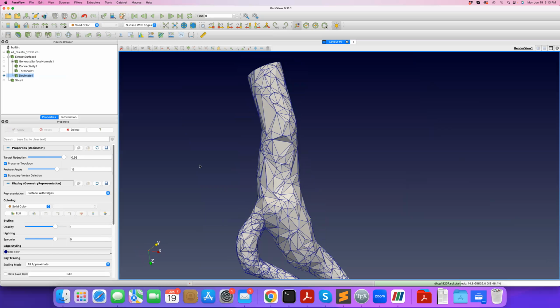Now I apply. And then I can select the things I'd like to visualize. In this case, I want to visualize pressure, so let me turn off everything else. Now you can see along this line, these are the coordinates along the line, and the y-axis is the pressure. So I can generate these graphs for data along the points defined by these 2 points. Okay. That's the main thing I wanted to talk about.